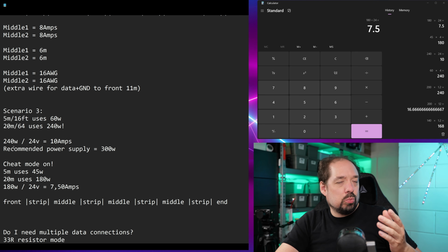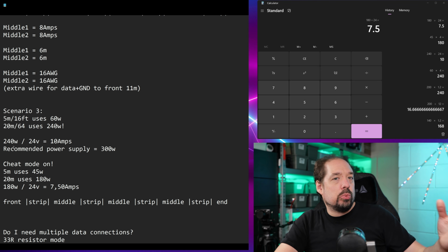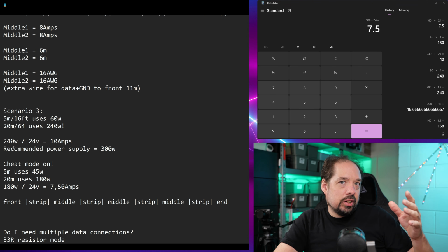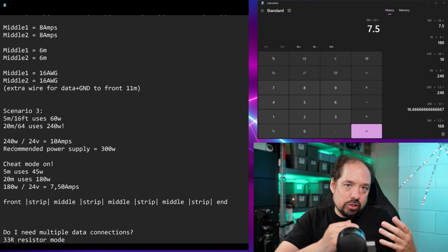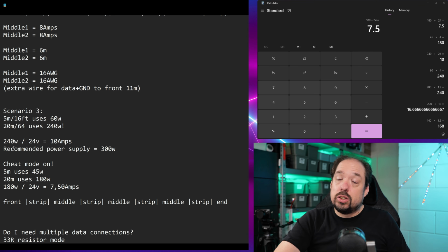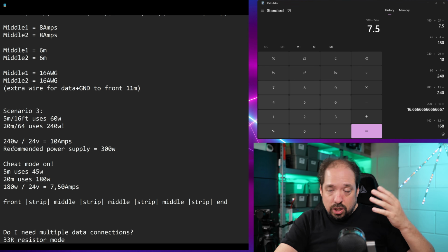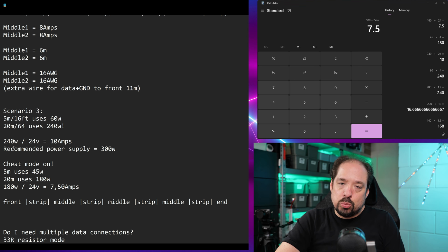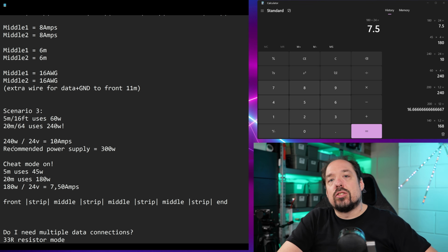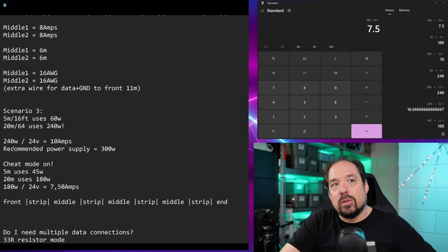Or maybe we don't care that much if it's full brightness power, or if it then encounters a scenario where it doesn't have enough, we can use the WLED power limiter, set it to 8 amps, and then if one of those scenarios would happen, it'll just lower the brightness slightly. Maybe we're okay with that. Or just, as I said, we're just going to do effects.